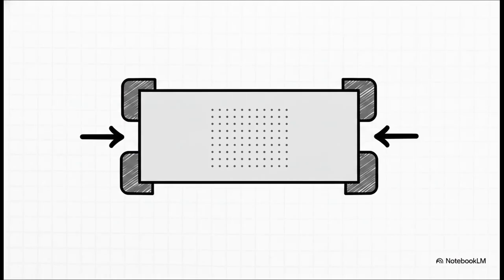The countermeasure here is extreme mechanical restraint and balance. We mitigate this by upgrading to low CTE materials, like glass core substrates. We make absolutely sure the copper trace distribution is perfectly symmetrical, and, perhaps most impressively, engineers attach physical metal stiffener frames around the perimeter of the die to forcefully hold the substrate flat, literally wrestling it into submission during assembly.